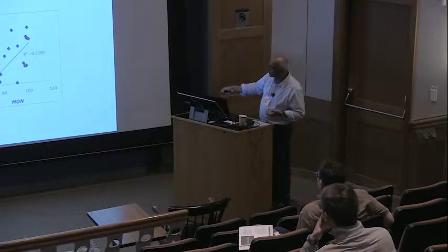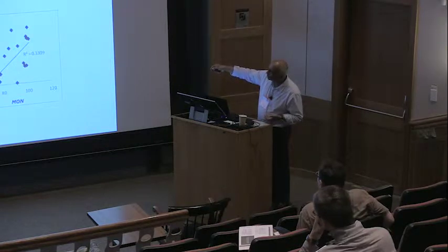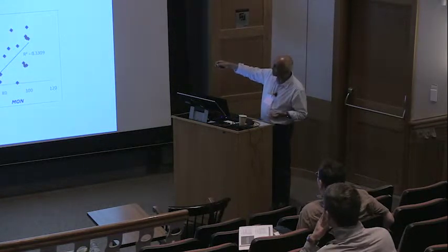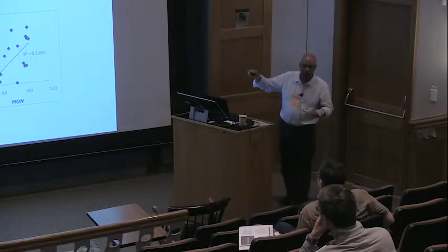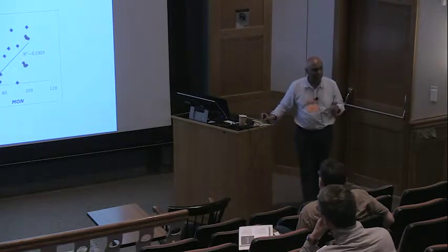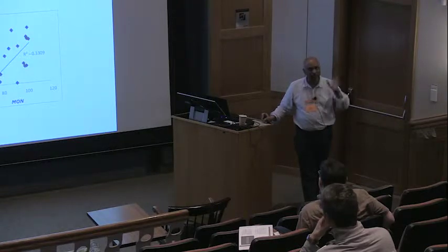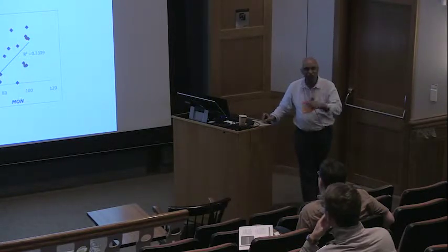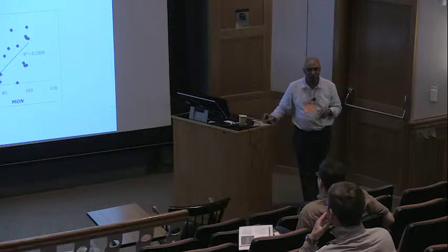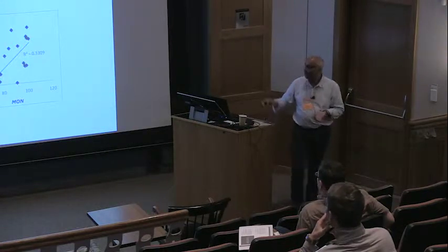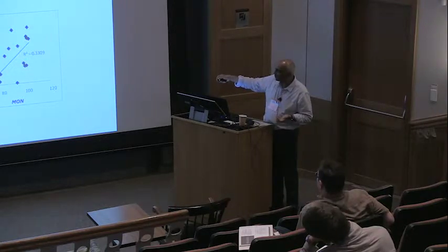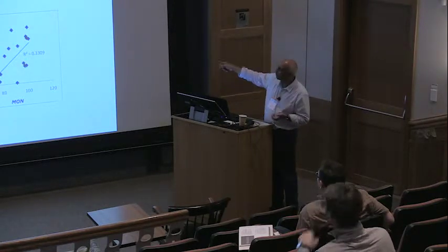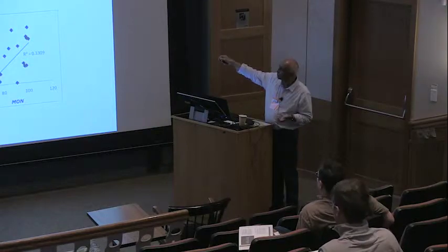And in fact, you can plot this pre-ignition propensity. I won't go into the detail, but for many of these fuels, Ricardo actually had a test procedure, and just like RON and MON, he assigned a pre-ignition resistance to different fuels. We know the laminar burning velocity of many of these fuels as well. And if you plot this, there is a good correlation, as predicted by this.